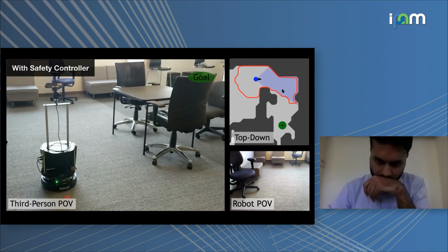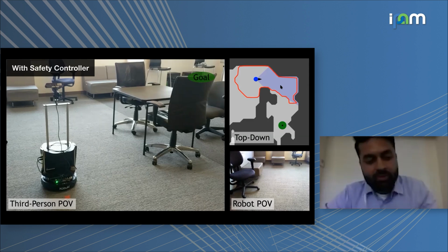You say the uncertainty is 5 centimeters. That's typically not what you get back from one of these state estimation systems, right? I agree they give you an uncertainty, but they give you some kind of distribution of uncertainty, not a single number. Right, absolutely. What we are doing there is thresholding that distribution, say up to 2 sigma, for example. So we are not fully leveraging the stochastic nature of that uncertainty. We are converting it to deterministic uncertainty and using that, which certainly is an assumption we are making and mathematically not necessarily the right thing to do. We may want to use the full distribution, but that's what we are doing right now.